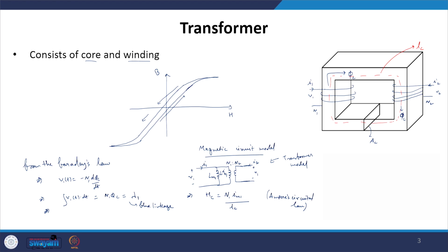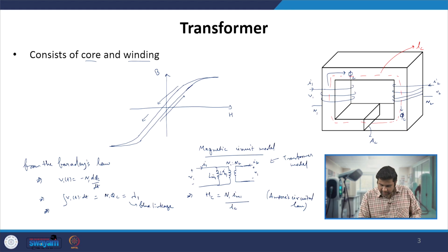Now, because of that, let us see what particular things we get. If you look very carefully, this is the integration of excitation voltage V1 which is applied in one of the windings in the transformer. Since we got this, we can also write that the current going into the magnetizing inductance is the one which actually leads to the magnetization in the core, so we can write Im1 to be 1 by Lm1, where V1 is the excitation voltage, some arbitrary periodic voltage which has been applied.